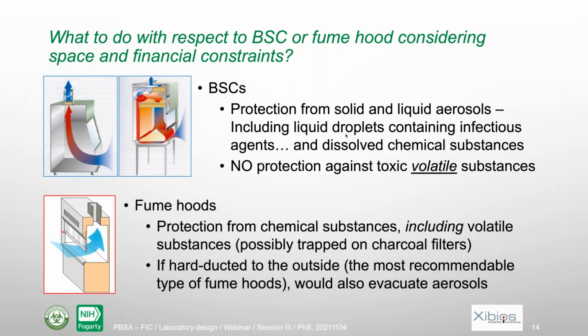Fume hoods are designed to protect from chemical substances, including volatile substances that could possibly be trapped on charcoal filters. So you have the exit of the fume hood. If you connect it to a duct that sends the air to the outside, it will also evacuate aerosols. It will not necessarily stop the aerosol through a filter, but at least you will eliminate the aerosols from the lab. So it will also offer some protection of the people working in the lab from those aerosols.